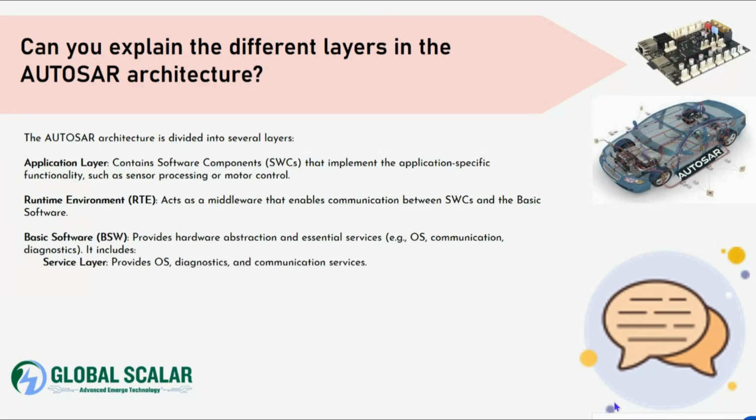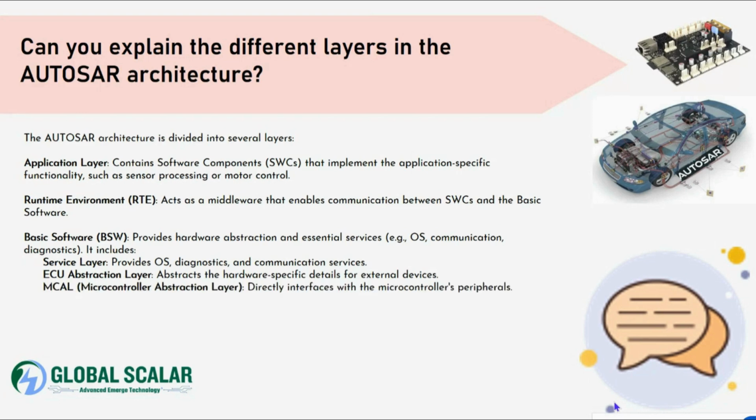It includes the service layer, which provides the OS and diagnostic communication services. The ECU abstraction layer abstracts the hardware-specific details for external devices. MCAL is the microcontroller abstraction layer. It directly interfaces with the microcontroller peripherals. And the complex device driver, CDD, is used for non-standard and time-critical functionalities.